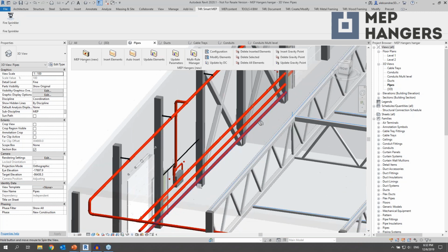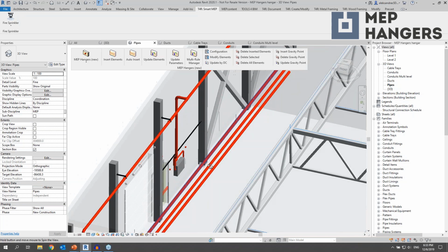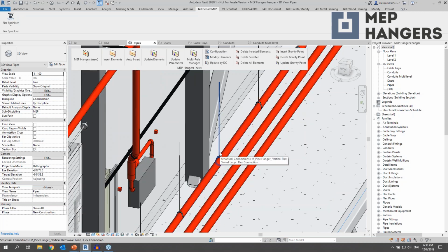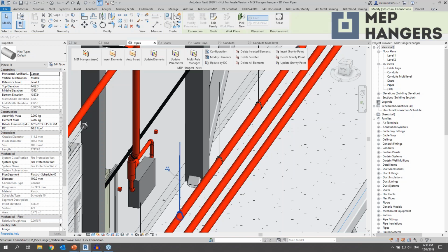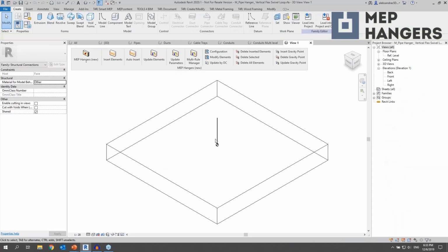It's called Sort Mark, and it helps to create better schedules. It helps to, like it says, create marks in different elements, not just MEP, not only hangers, but any element in your project. It's a pretty useful tool. But here I will show how it's possible to extract some information into the hanger from MEP element. So this, for example, has parameter system name, fire protection wet 2. Maybe you would want later to filter out your hangers by system name to which they belong to.